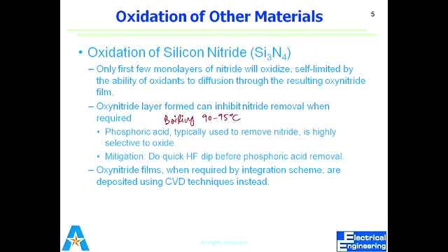Yes. So what does silicon nitride turn into when you oxidize it? Silicon nitride would be, that is oxynitride. Yeah, that is oxynitride that is actually formed when you oxidize silicon nitride. But you cannot grow a thick layer. In that case, it would be only a very few nanometers of oxide layer that can be grown on the silicon nitride. What use is it?